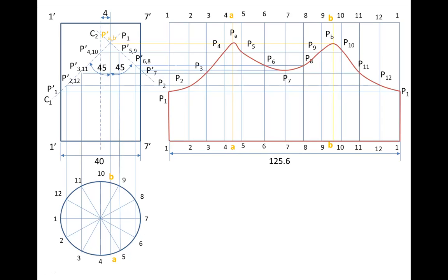So this will be the development of the surface of the cylinder when it is cut by two planes. Now if you use this sheet and fold that, it will give you the diameter 40. At the same time, it will give you the front view like this. So the upper part will be removed now. All this part is removed. So this is the answer.